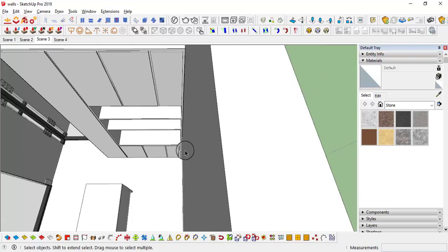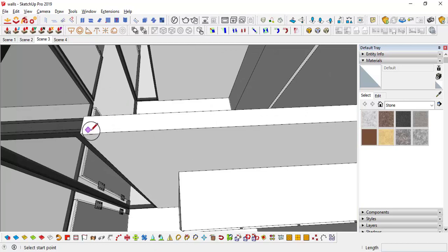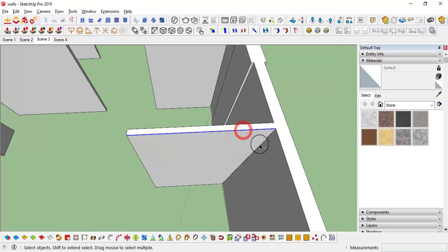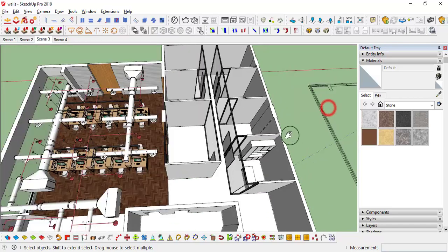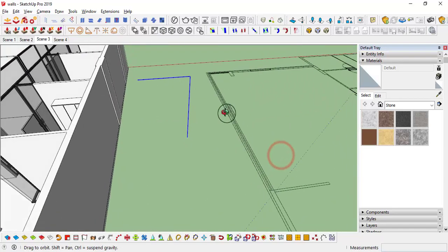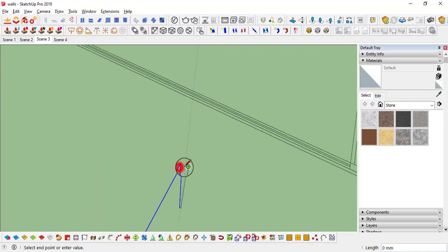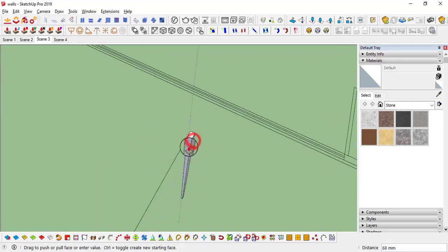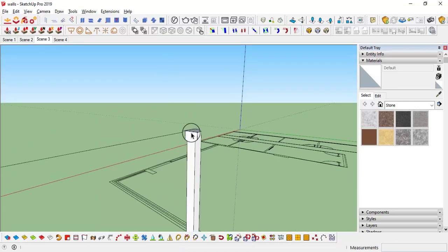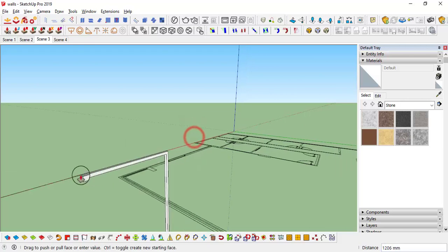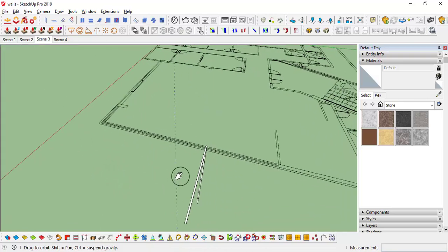So for the easiness, I will make a line, or we can do one more thing. Select this, Control C, Control V. Okay. Next, L, enter, in this direction 1.5 inches in upward direction up to here, and push pull 1.5 inches, and this line, M, control 1.5 inches, push pull up to this line. Okay, this one is one rafter,